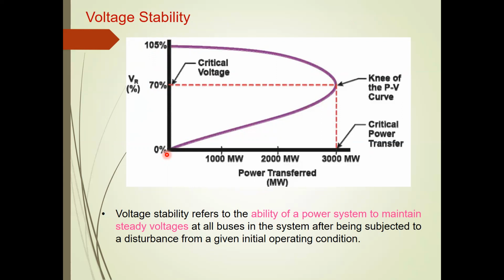Okay. Just see. Normally, voltage stability we discuss for high bus voltage. Actually, it could be 230 kV, it could be 400 kV, it could be 765 kV, and so on. Voltage stability, we generally don't discuss for 400 volt, or maybe for a distribution network, or for an 11 kV line or 33 kV line. Voltage stability, mainly we say it for much higher voltage.